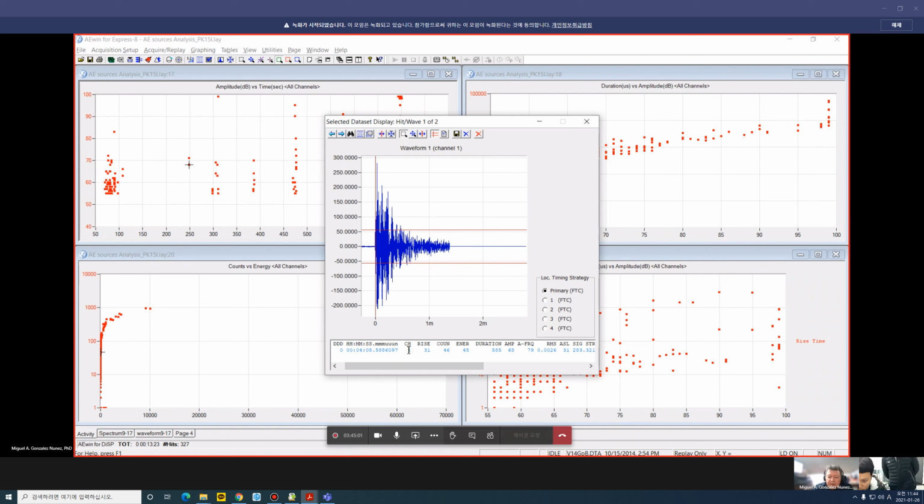You see what channel detected the signal, the rise time, the number of counts, the energy, the duration, the amplitude of the signal in decibels, the average frequency, the root mean square, the average signal level, or ASL, the signal strength, the absolute energy, the partial powers.